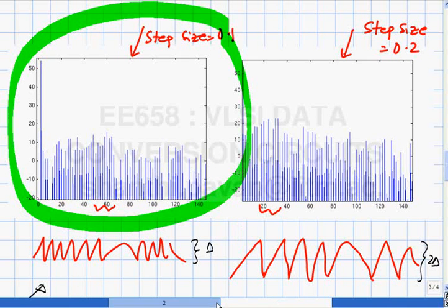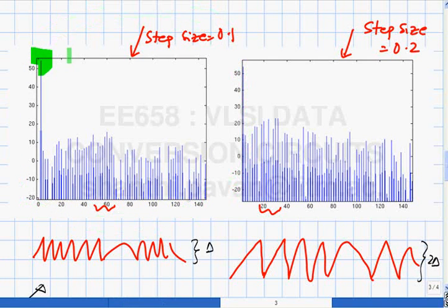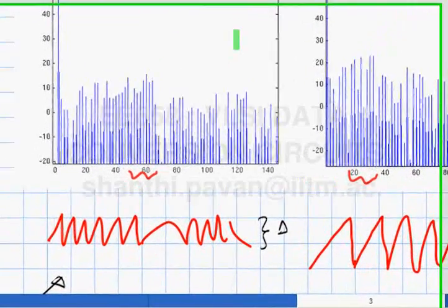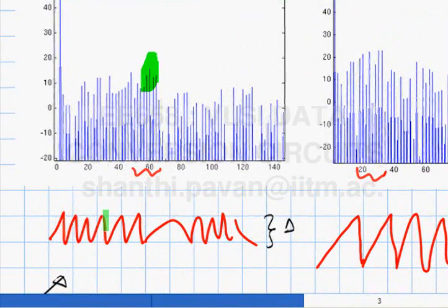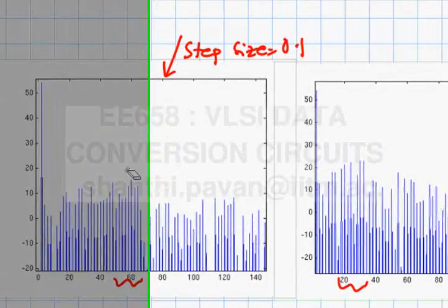A common mistake made by a lot of people is to look at this diagram and say, oh, this is 50, this is 10, so the difference is 40 dB, right? So 40 dB minus 1.76 divided by 6 should give you the resolution of the converter. That's clearly erroneous by a large margin, because if you consider this to be 10 dB, that's only this harmonic here. If I add up all this, there's a lot more harmonic power, noise power than just this peak here. So that will give you ridiculous answers.